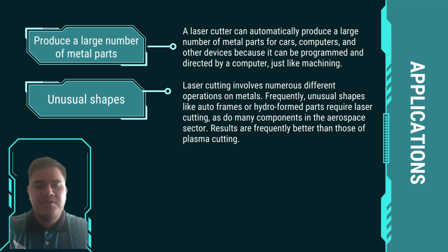When light particles with the same wavelength exit the laser resonator in the same direction, they form the laser beam. In the case of a CO2 laser, this beam may be in the invisible infrared region of the spectrum, or it may be of a different wavelength depending on the application. It may have a diameter of about 0.75 inches when it leaves. Then, one or more mirrors reflect this parallel light wave back into the focusing head. The beam travels through a number of lenses inside the focusing head after entering it. Naturally, this gives it focus. It then emerges from a nozzle and scorches anything it touches.